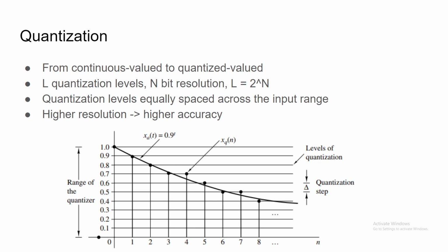The quantizer can be defined using three characteristics: its resolution, minimum input value, and maximum output value. Basically, the quantizer maps the input values into a finite set of values. In our case, we want the input values to be as close to the output values as possible. For our quantizer, how do we choose the finite set of output values and how do we map the input values into the output values, considering that we want our output values to be as close as possible to our input values?